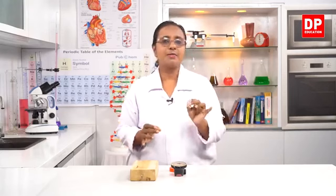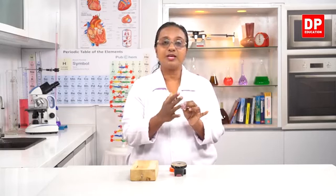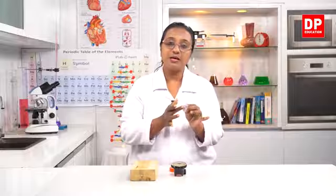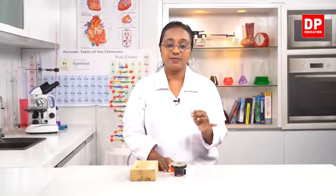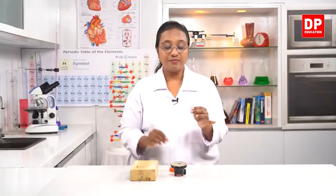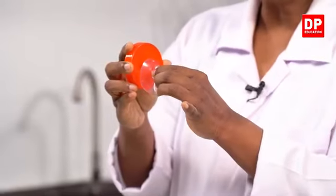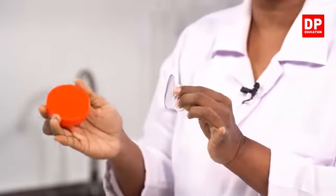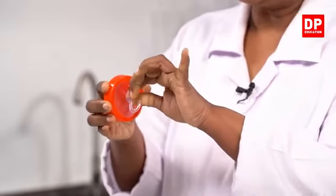So how does this rubber sucker function? Now you can see on this surface there is atmospheric air. So around it there is atmospheric air. So the pressure exerted by the atmospheric air acts on this surface as well as this surface. But when we press it to a surface, I'll explain it now and then I will demonstrate it. Now let's say if this is a glass surface, when I press it onto this surface, the air that is here will escape out. So because of that, if we just keep it this way, it won't stick.